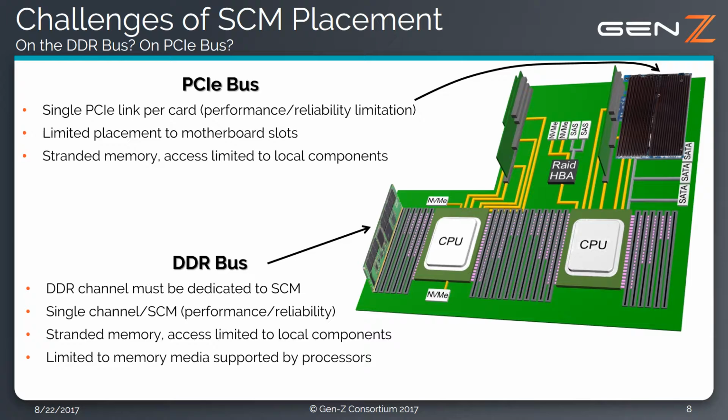These DIMMs are called NVDIMM-N. They typically have lower capacity than standard DIMMs because of the persistency circuitry, but they are very fast and operate well on the DDR channel. Another type of NVDIMM are NVDIMM-P DIMMs that utilize storage class memory natively. These DIMMs have logic that allow the storage class memory to operate on the DDR memory channels.